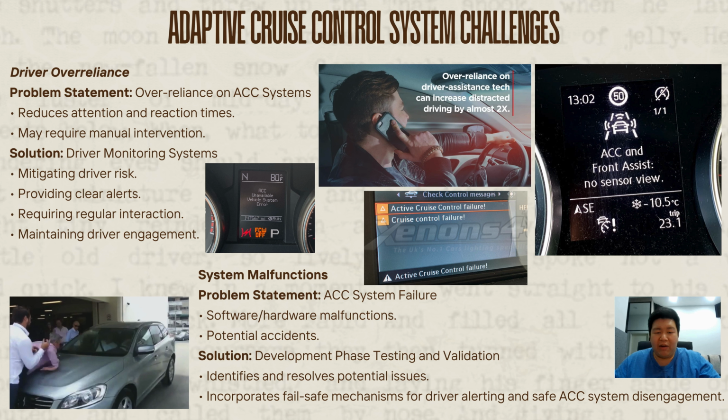Additionally, software or hardware malfunctions can cause the ACC system to fail, potentially leading to accidents. Rigorous testing and validation during the development phase can help identify and resolve potential issues. Incorporating fail-safe mechanisms that alert the driver and safely disengage the ACC system in case of a malfunction is also crucial for ensuring safety.